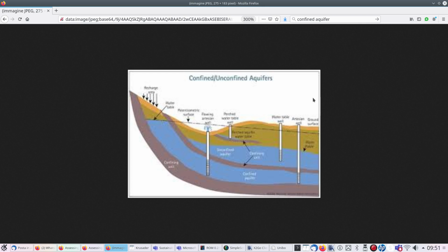This aquifer, phreatic or unconfined, is vulnerable to pollution and usually placed at a higher level with respect to confined aquifers. Confined aquifers, also called artesian aquifers, are under pressure and are more protected with respect to contamination. They can climb up along wells and can, in some cases, deliver water without pumping. You have to have clear this difference.